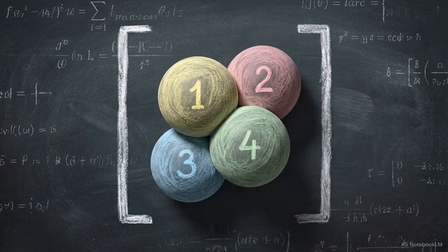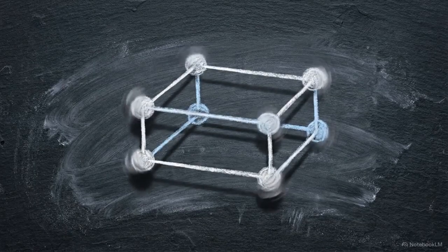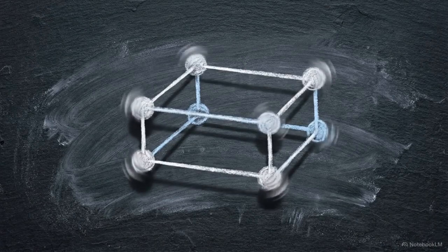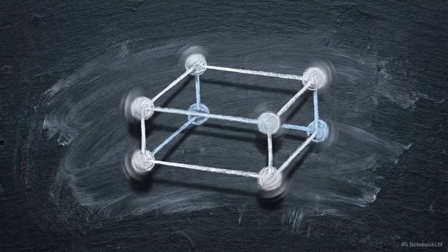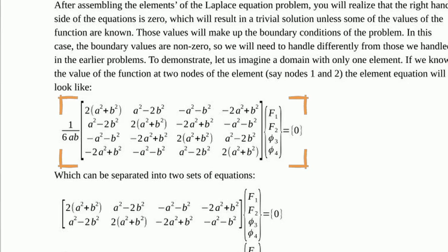A standard finite element assembly combines all 4 of these nodes into one rigid matrix equation. In this combined state, solving the system is mathematically impossible. The known constants and the unknown variables are locked together within the exact same vector. To solve this basic 4-node model, we have to algebraically tear the matrix equation apart along the precise boundary lines we just drew. This is the raw, assembled 4x4 Laplace matrix for our single element, completely unprocessed.